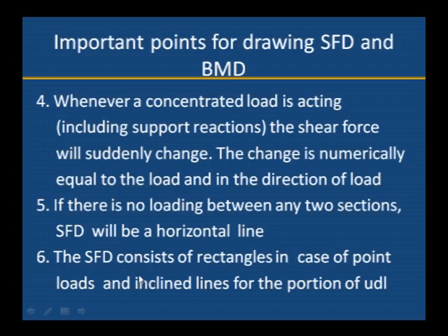The shear force diagram consists of rectangles in case of point loads and inclined lines for the portion of a UDL. If it is a point load, then the shear force diagram will be rectangles. If it is a uniformly distributed load, it will be inclined lines.